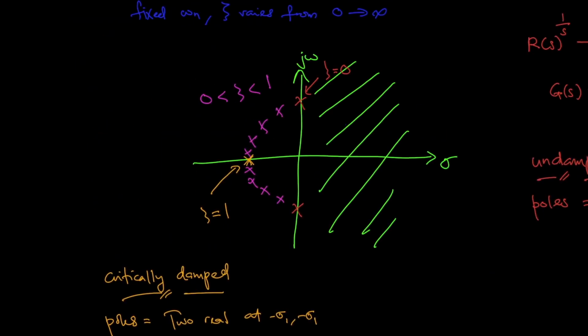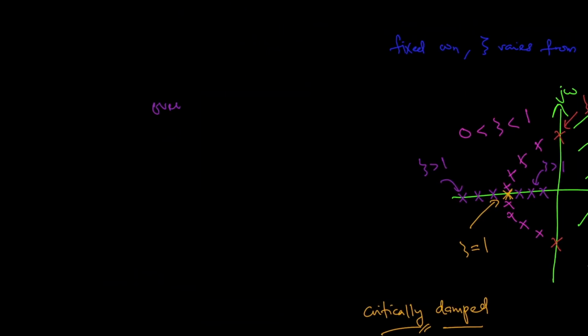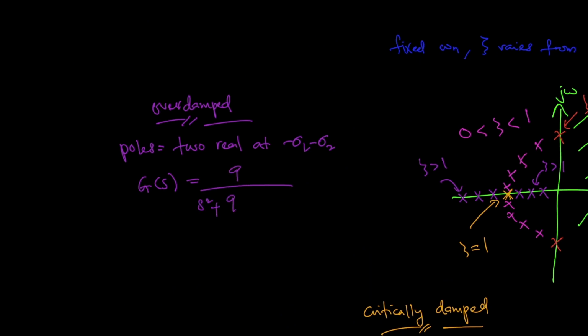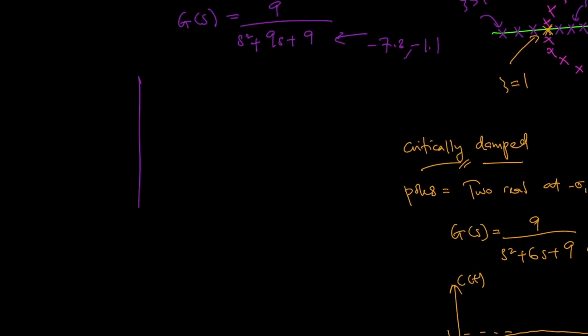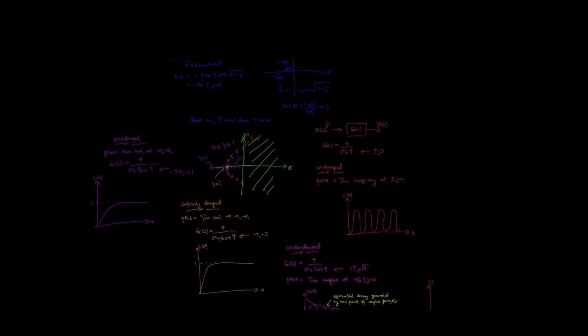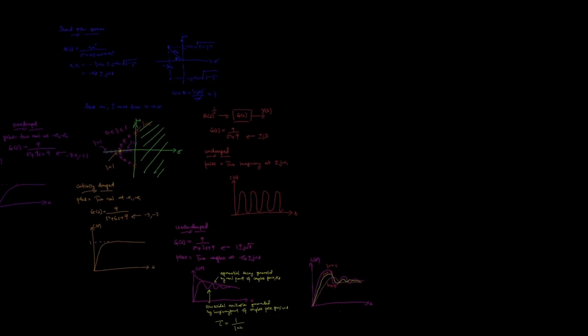Finally, for an overdamped system, zeta is greater than 1 and the poles are located on the real axis of the S-plane. The function has a pole at the origin that comes from the unit step input and two real poles that come from the system. The input pole at the origin generates the constant forced response. Each of the two system poles on the real axis generates an exponential natural response whose exponential frequency is equal to the pole location. We see that the poles tell us the form of the response without the tedious calculation of the inverse Laplace transform.